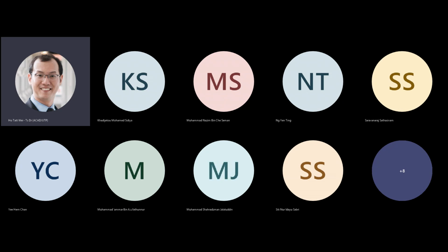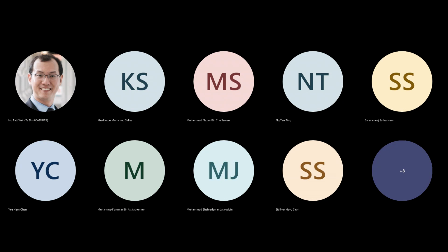And then some dielectric coefficient, and this is a material property. This is a property of the geometry, the size of your transistor. So I have the ability to change the capacitance of my transistor here. And I have some ability to manage the current.